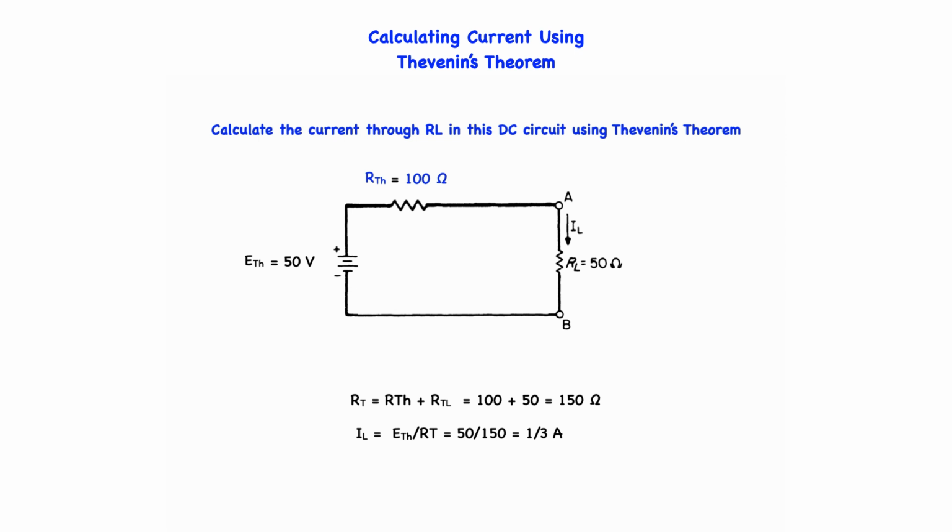With respect to the terminals only, the Thevenin circuit is equivalent to the original linear network. Changes in RL do not require any recalculations for this new Thevenin circuit. The simple series Thevenin circuit can be used over and over to solve for load currents each time RL is changed.